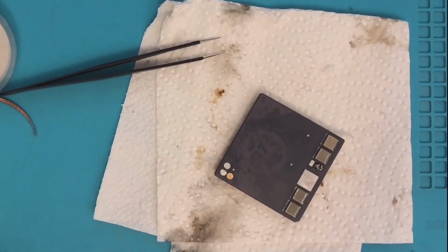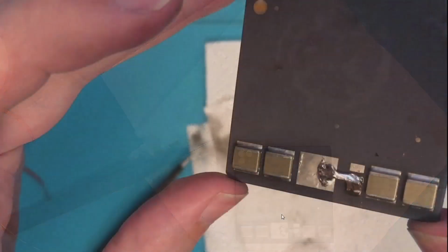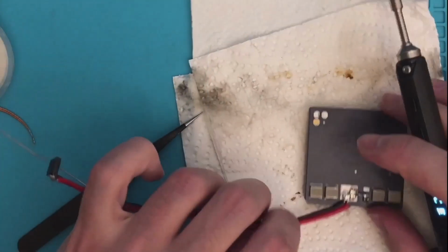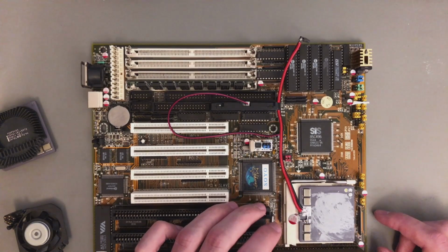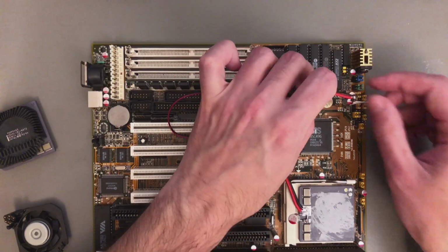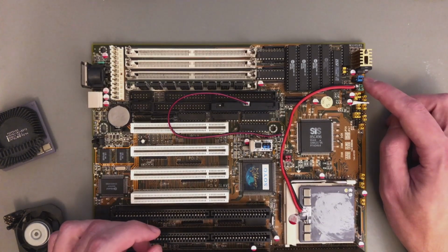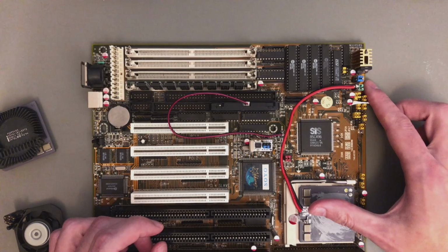And then just to make my life easier, I also soldered the wire from the middle pin. And now I have a very nice large target here where I can just connect my voltage input. And this is what I did here. Maybe in the end I also added an extra large electrolytic capacitor, 1,500 microfarads. And this nice cable just goes in and plugs here. And that's all. Very nice, right? Now the very high voltage settings here may be a bit unusable because of the high currents, but up to 4.1 volts this goes very stable. In the future I will make a new custom voltage regulator specifically for these CPUs.